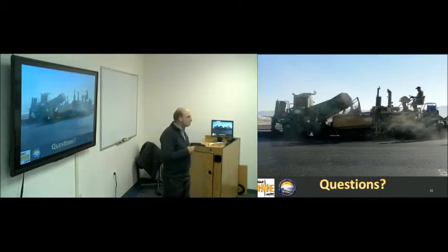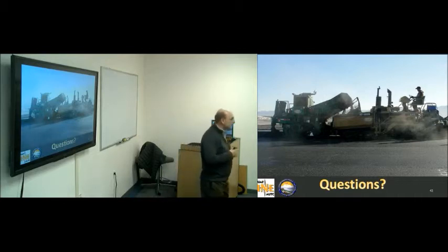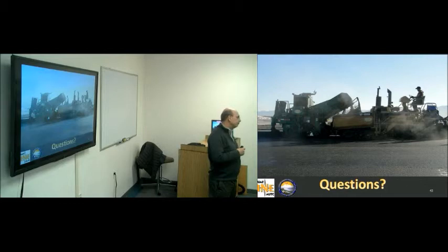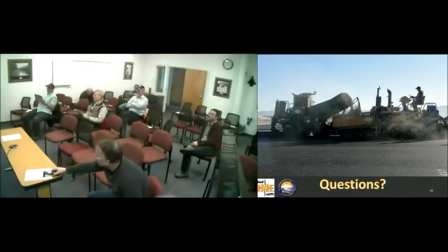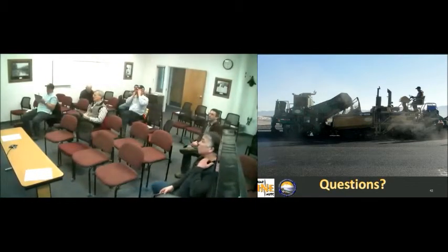Billy, the IRI roughness is trending up or worse, is that correct? Trending up is worse, yeah. And do we have resilient modulus data on our material sources? Do we have modulus data on our main pits? We have some. Okay. And Newt Bingham has been doing a good job of going around and measuring those with a falling weight deflectometer and back calculating those properties. Okay, so they're all back calculated.